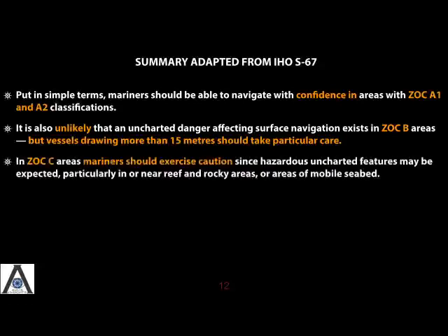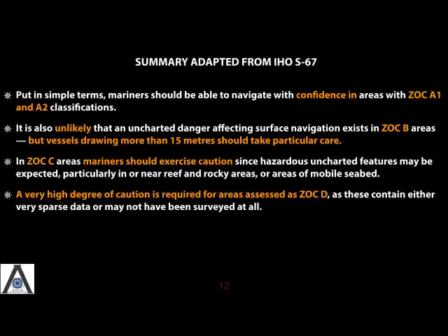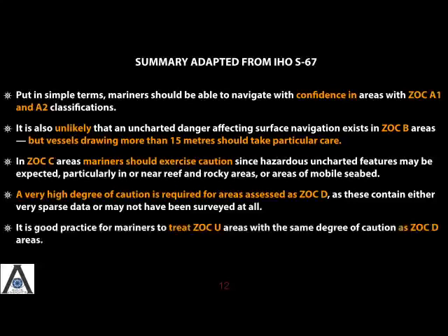In ZOC C areas, mariners should exercise caution, since hazardous uncharted features may be expected, particularly in or near reef and rocky areas, or areas of mobile seabed. A very high degree of caution is required for areas assessed as ZOC D, as these contain either very sparse data or may not have been surveyed at all. It is good practice for mariners to treat ZOC U areas with the same degree of caution as ZOC D areas.